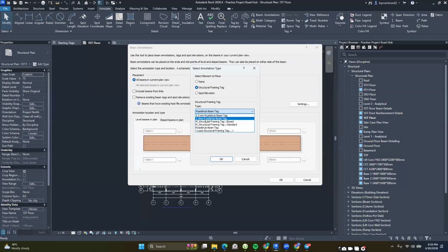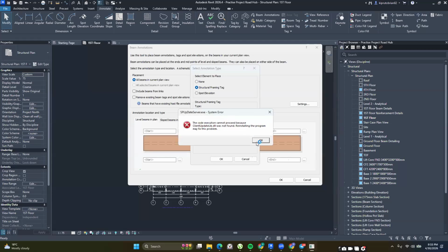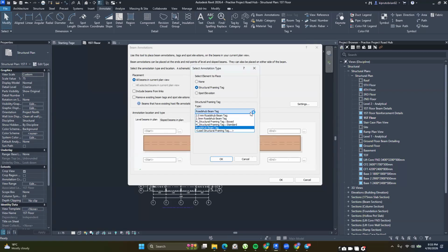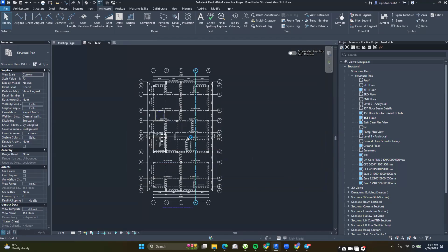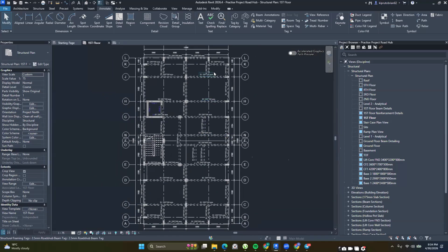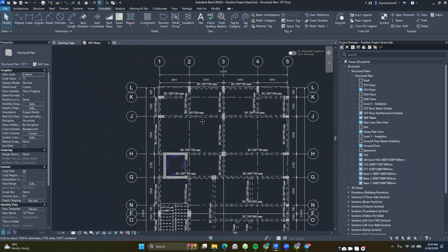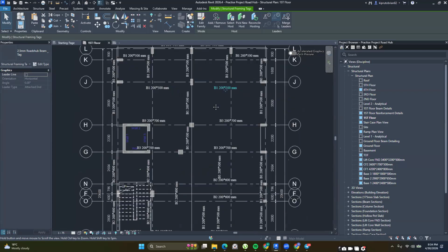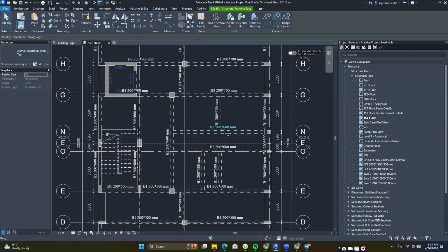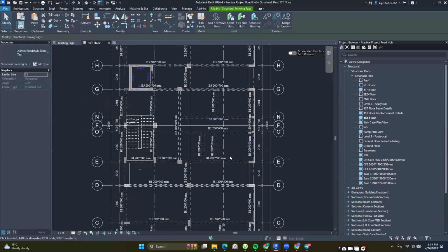You could have as many sizes as you want, so that based on the scale that is suitable for that particular project, you can find a suitable tag. So if I place 2.5 millimeter now, I think it would look a bit better than what we had with the others. And then once you have this, the areas that are just having a bit of flashing, it is just easier to move them manually than adding tags for each beam manually.